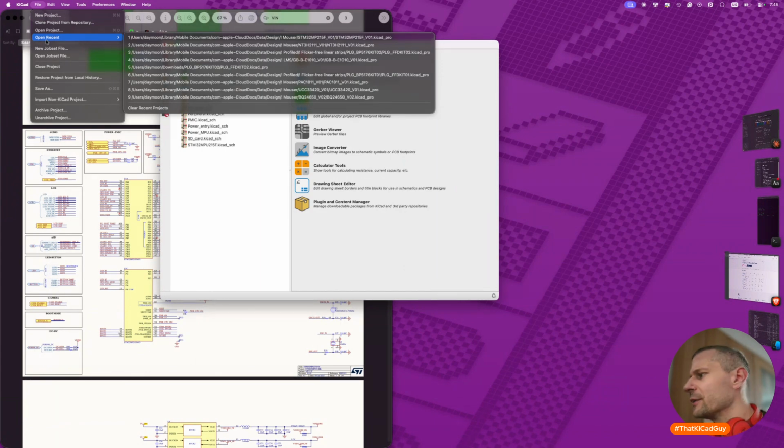I will copy the symbols. Yeah, I will open each block separately in the schematic editor, copy the blocks I need, and paste them into my schematic. So you will see, I will run the KiCad application and separately open the schematic editors. That's the best way, I think, to set the limits, set the boundaries between my KiCad project and the imported one.